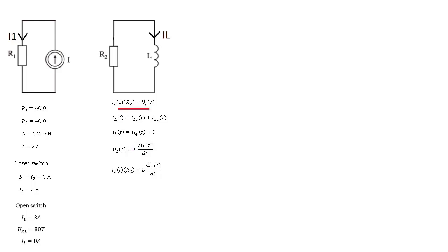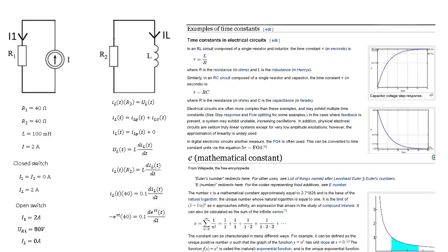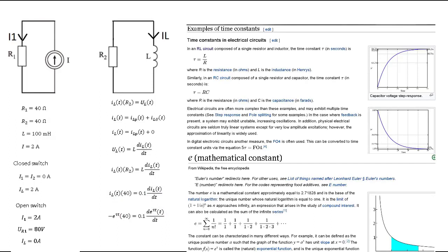I put this term into our new equation with a derivative, obtaining a new equation. Known values for inductance of the coil and resistance can be substituted into the formula. In the next step, the current of the coil is written in a different form. I have used the concept of time constant and Euler number. This number is on every scientific calculator, which will simplify calculations.